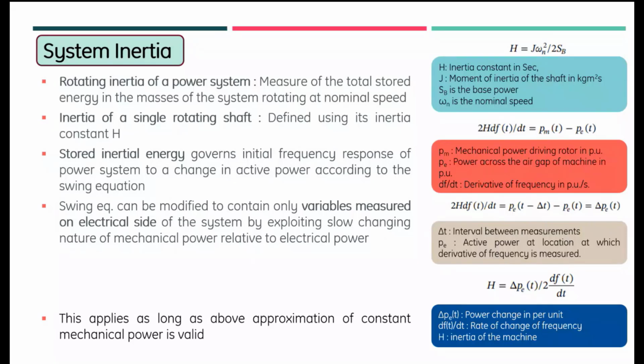So what we can see is that I want to know how much is the regional inertia contribution from power system A, and what is the regional inertia contribution from power system B, and the combined inertia contribution. The combined inertia will be the summation of the individual inertia of each area. So what I can do is put PMUs on the lines which connect A to B.